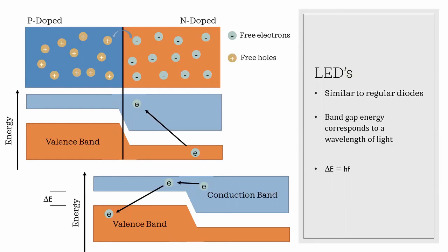And there are tons of applications for semiconductors beyond this, but this is the most common one that everyone should be familiar with, and it's the one we'll be using first. You can make a thermistor, a device that changes the conduction across it based on the temperature of your system. Or you can make a reverse LED, where if you shine light on it, the energy from the light actually gives you the required energy to jump over the band gap and start current flowing. This is how you can make some kinds of sensors.